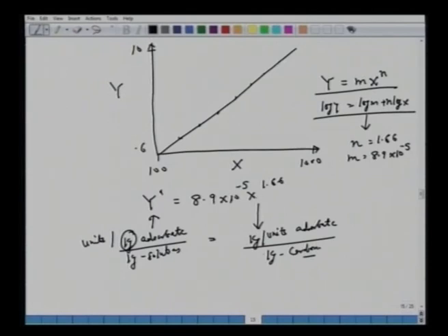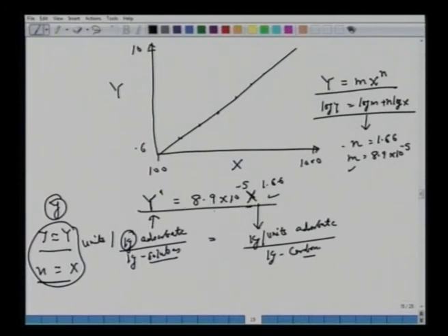And also notice this, that when we write solution, here this should have been a small y, all right. Essentially this nomenclature, capital Y and capital X, we use for solute free basis, but here it's a very small amount of solute, so approximately y has been approximated as capital Y, x as capital X. All right, one can still work with a small y and a small x, but without much improvement in the accuracy. So whenever we have dilute solutions, we have seen in the case of absorption also that in general one can still use capital Y and capital X and get a straight line for both the equilibrium as well as the operating line. So after this we get n, m, we have the Freundlich isotherm.